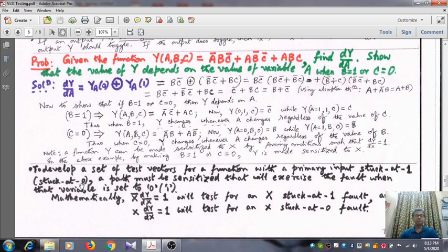So in order to test a cut off NMOS transistor, the gate voltage should be made logic 1. Why? Because the output voltage, whatever be the value when the transistor is conducting, would have given some particular value, and now that the transistor is suffering from the fault, definitely the output will be something different.